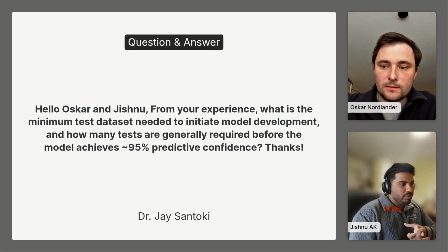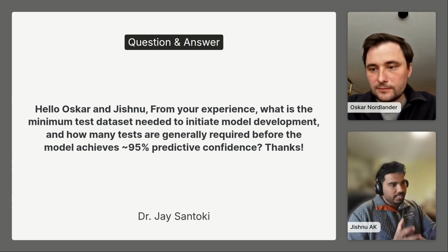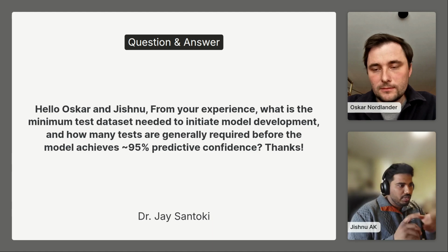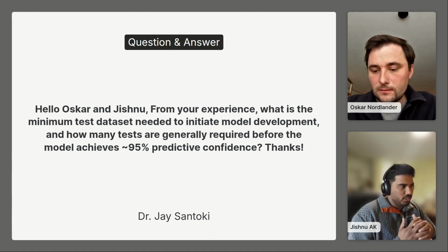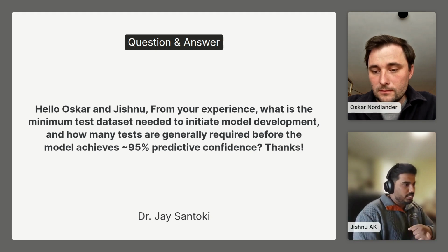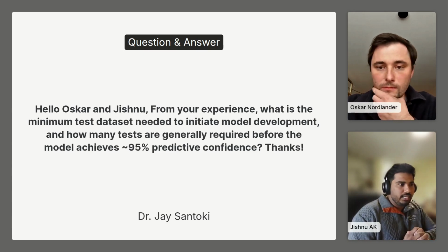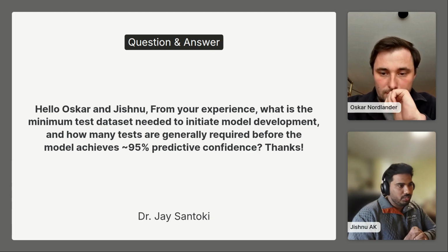The number of experiments needed for calibration depends upon the operational envelope, that is, the temperature range you want to consider, the C rate range, the SOC windows, etc. It also depends upon cell chemistry. If there is silicon present in the cell, we would need some additional tests for that. So there's no definite answer, but for the use case shown in the previous slide, we used about 7 cyclic aging conditions and 3 calendar aging conditions for the model calibration.